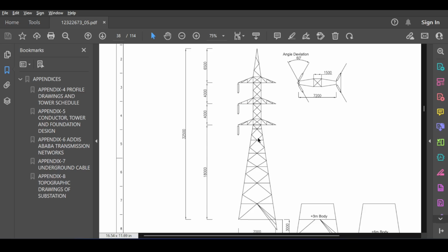Now during the modeling here, and that's the reason why I decided to split it into modeling only without loads, I will be giving a lot of practical details here and from the field details. You see, what we usually assume is that those chords are made out of one piece. I know it looks like a truss, and I know you would be inclined to basically model each and every one of those elements as one piece. But in reality, what ends up happening is that we use one full piece for those chords.